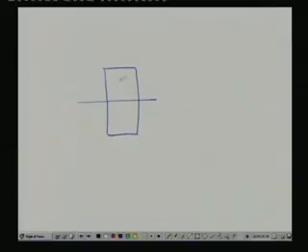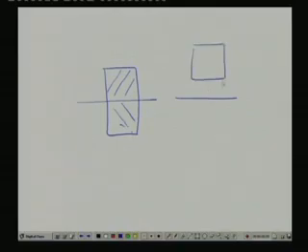Suppose we take this mass and place it arbitrarily at a distance. Then we are getting it more away from the neutral axis. Once we go more and more away from the neutral axis, we are increasing the I. Of course, y also gets increased, but it does not matter, the overall value of I by y will increase.